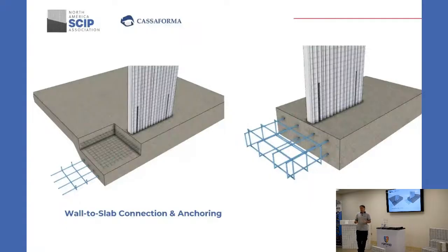That rebar is usually a number 3. You will place it every 1.5 feet usually, and it will have a length of about 16 inches. Usually you place a mechanical connection product, epoxy, for that. Of course, it also depends on the seismic area. That's about calculation, and you shouldn't take what I'm saying as 100% certain. It depends on every project.